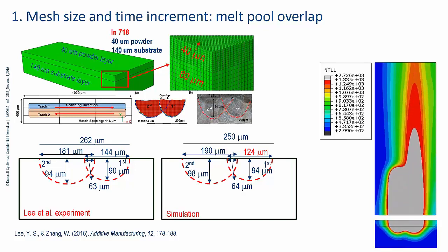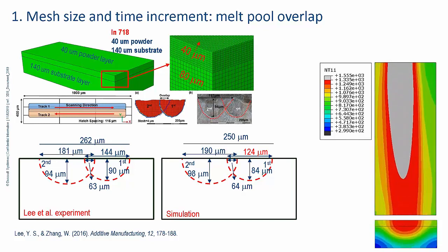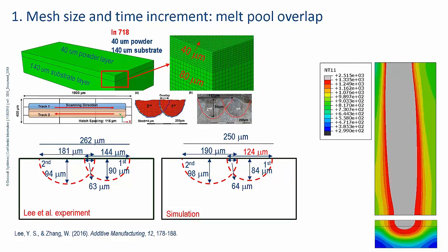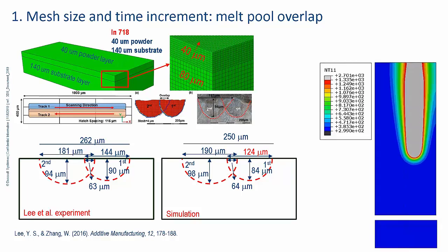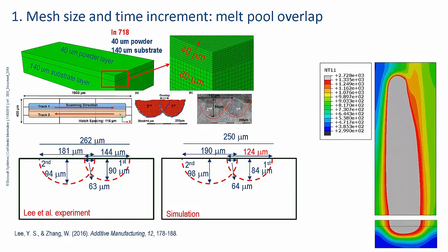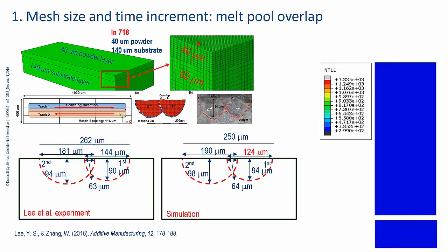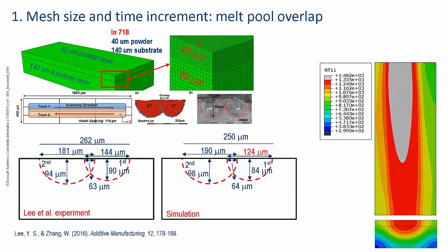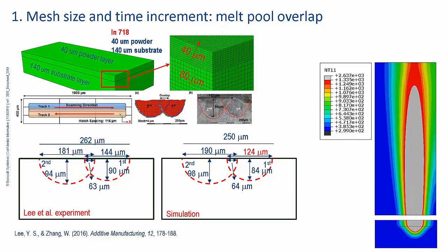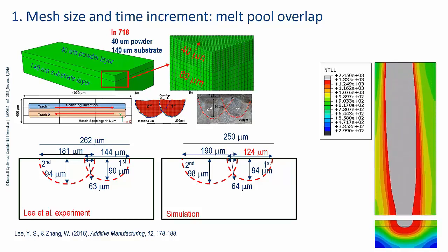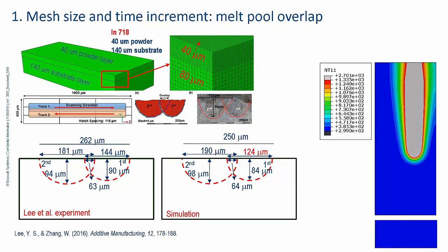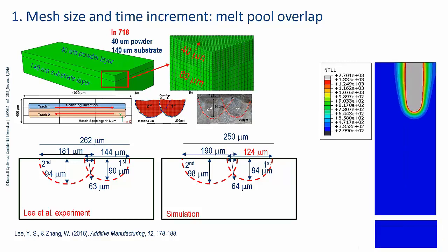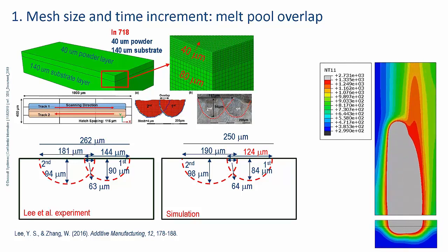As we know, the melt pool is created due to the interaction between the laser beam and fused powder. We use fine meshes, for example, several elements in the melt pool, and small time increments in the areas of interest. So the model is able to capture three major items. First, the non-uniform energy density distribution. Second, high cooling rate, like thousands of degrees Celsius per second. And third, high temperature gradients associated with the melt pools and their vicinity.